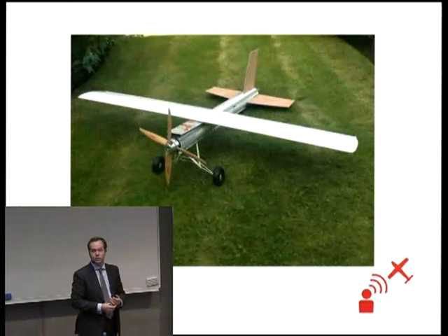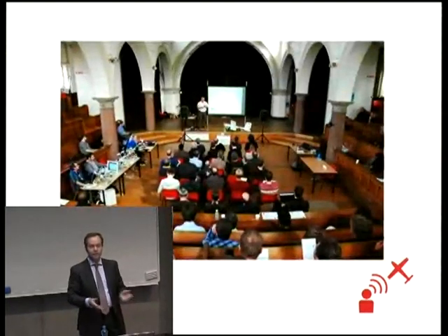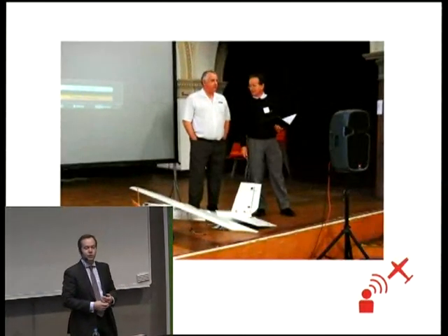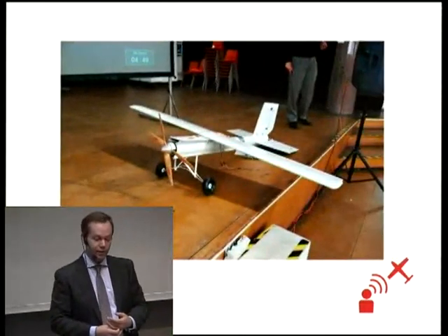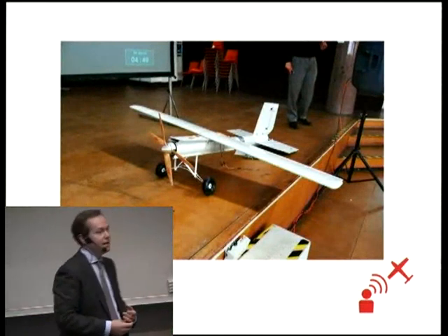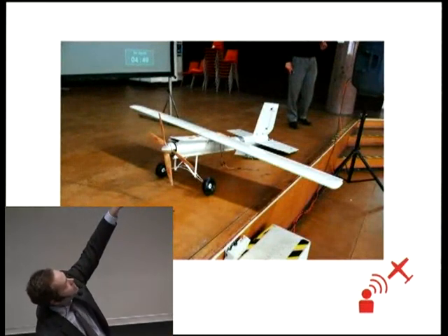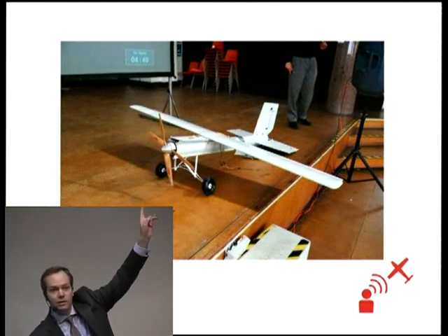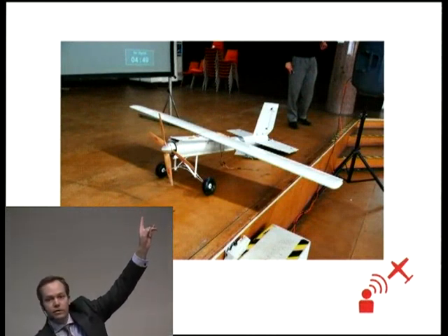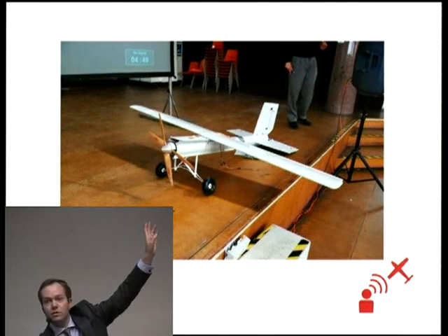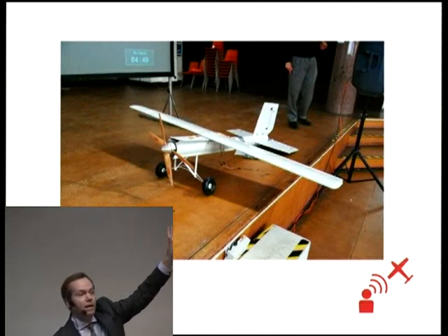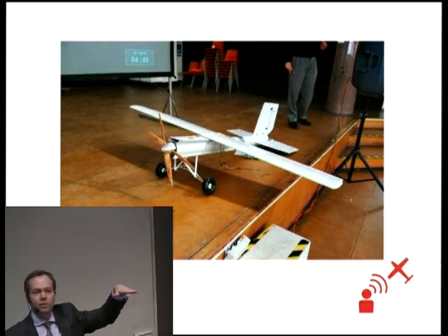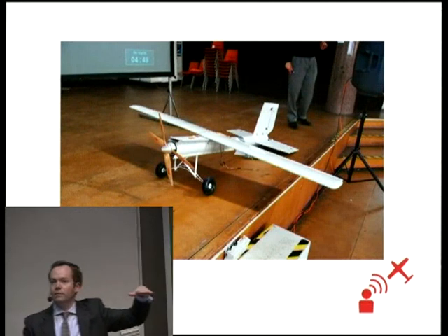The first version of it was displayed here, and at the Open Source Hardware Summit a couple of months ago. That's Eddie in white, showing a slightly more advanced version of the airframe. Little details on it, again, quite revolutionary. You might be able to see on the tail, do you see two black parts on the tail there? Those are the servos to control the flaps and so on the aircraft. Each control surface has two servos, so that when one fails, the aircraft does not fail.